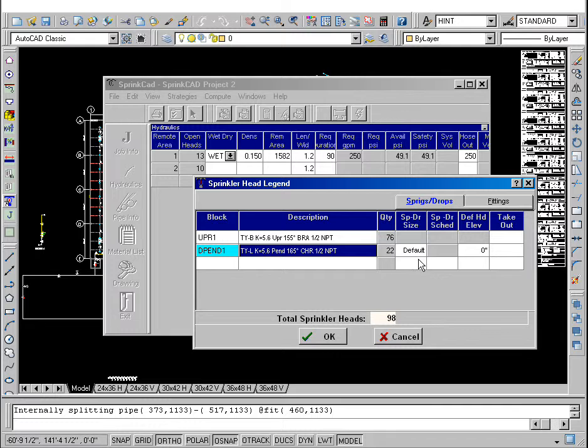The columns to the right of the description are used to specify the drop pipes. Using the drop-down lists, select 1-inch Schedule 40. The head elevations will be 8 feet. Press the Fittings tab. Pick Default, Default, Default from the pull-down lists for the T-run, T-outlet, and end elbow columns. If there is any value in the qualifier cell, highlight it with the mouse and press the backspace key on the keyboard to remove it. This will yield threaded fittings at the branch lines for the heads.